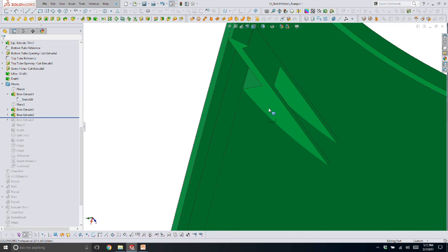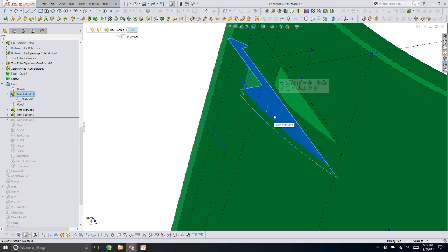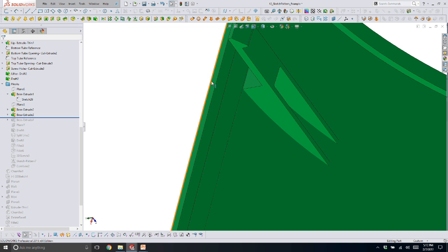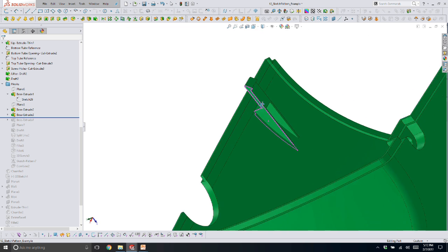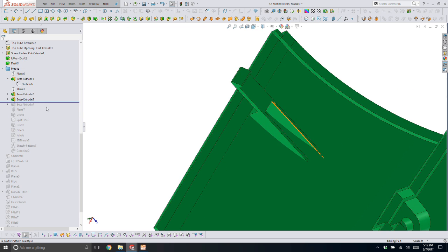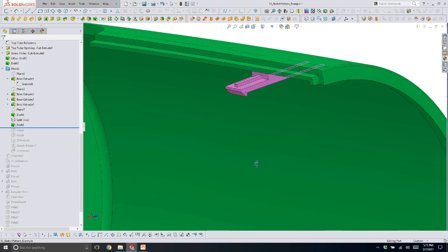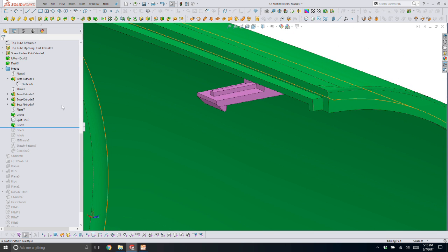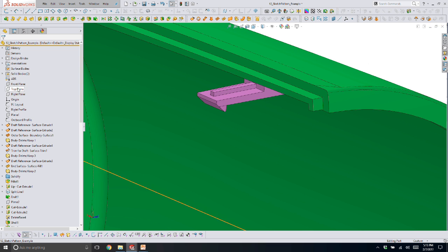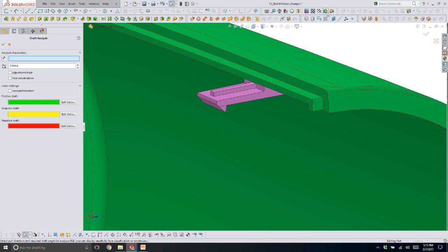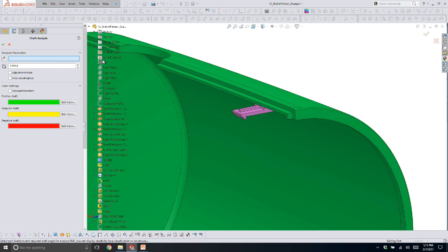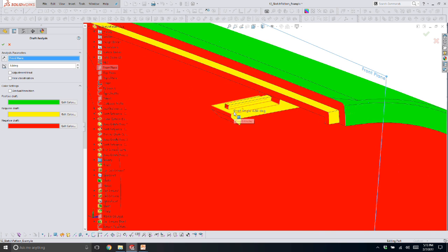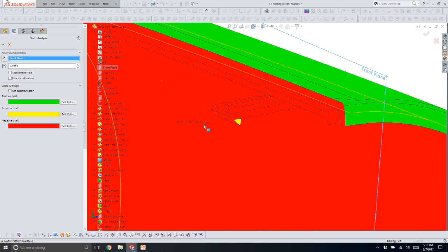Here, I am trying wherever possible to pierce my geometry through the main wall of the part. Instead of just going up to the surface, I would go offset from surface by a little bit, a millimeter, 40 thousandths, a third of the nominal wall. Then I had added some additional detailing. I added all the draft to this guy for both the lifter that forms the underside, plus the main open-shut action here. And if we look at the front plane of this part, once again, I get bit by SolidWorks' inability to pre-select draft.